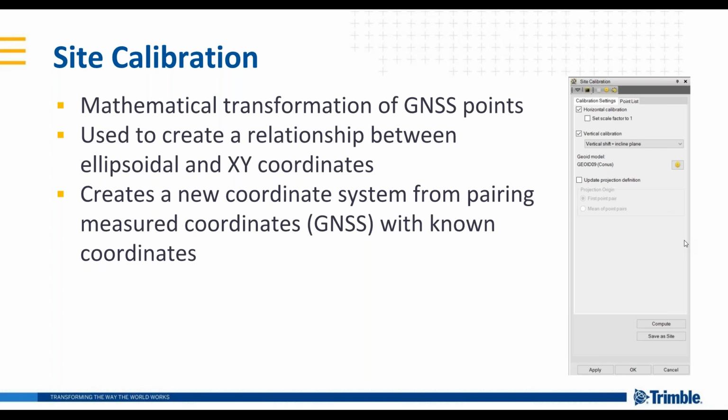And site calibration is a 3D transformation, so you'll see as we go through the demo, but we can do just horizontally, just vertically, or a combination thereof.